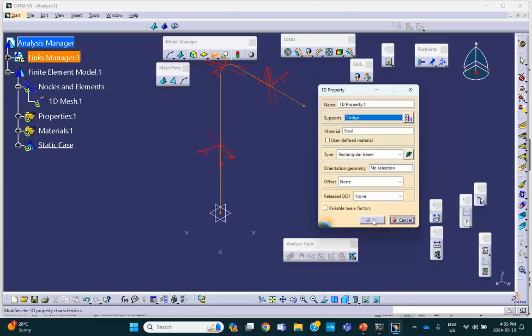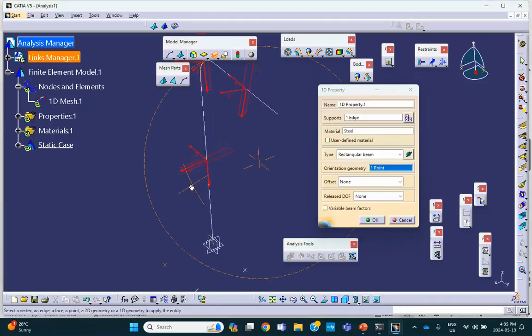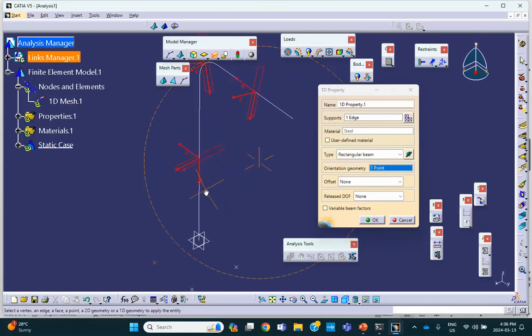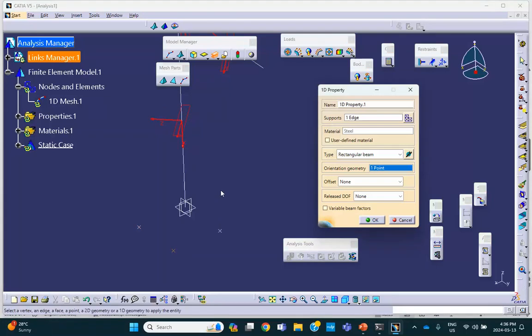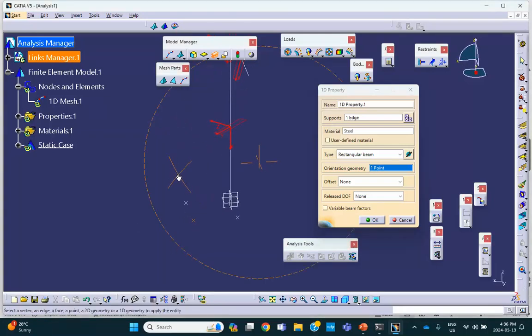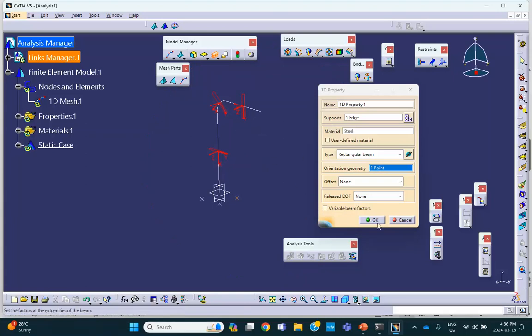You see? Now it won't even let you close it, because you have not selected the orientation point. Right here, no selection. You select this. Let's choose point 1. Watch what happens to this cross section where I select point 1. It turns it so that it looks kind of like that. If you select a different point, it turns it again. You can see that. And finally, if you select this point, it changes the orientation. The moral of the story is just, if the cross section is rectangular, there is more work you have to do, okay? Because the orientation of this is important.